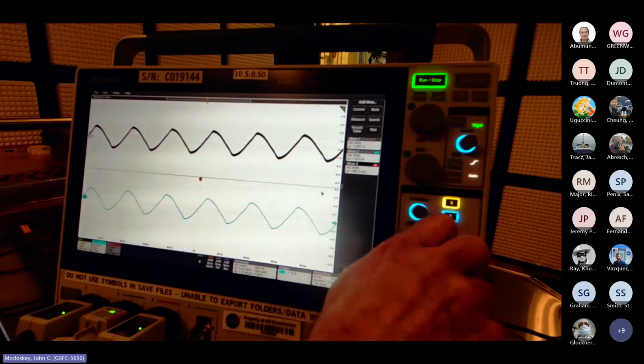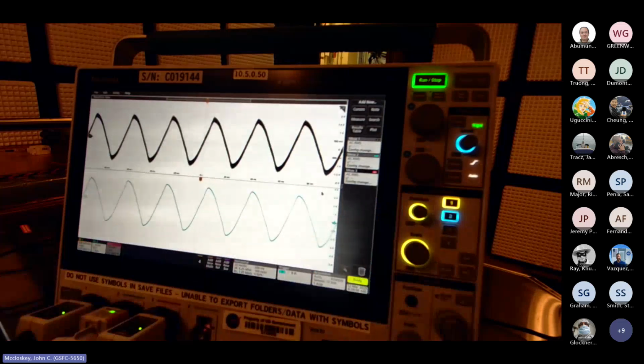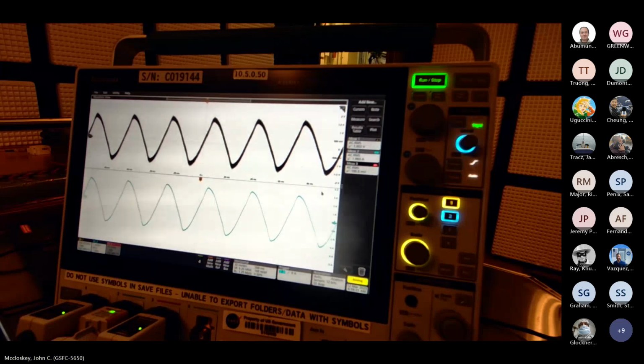And oh, you can also see the waveform looks a little weird. It's not a completely clean sinusoid. So if you're just reading this, sometimes people will read the voltage just into an RF power meter or something like that, or maybe an AC voltage reading off of a DMM or something like that. I definitely recommend you actually look at it on a scope because you'll miss things.